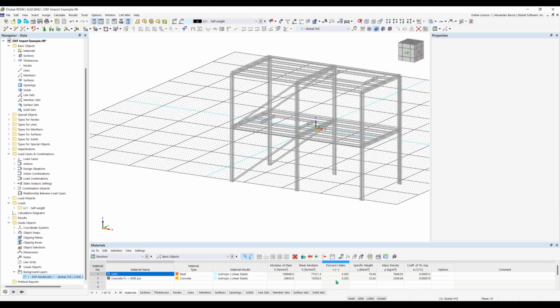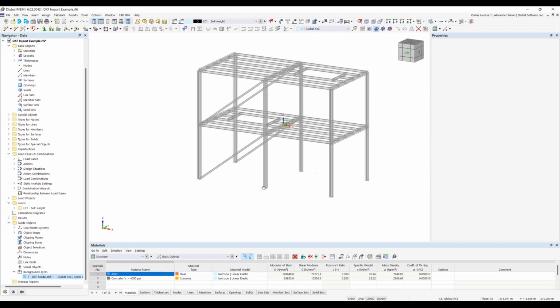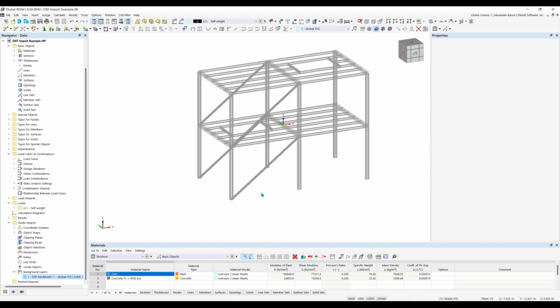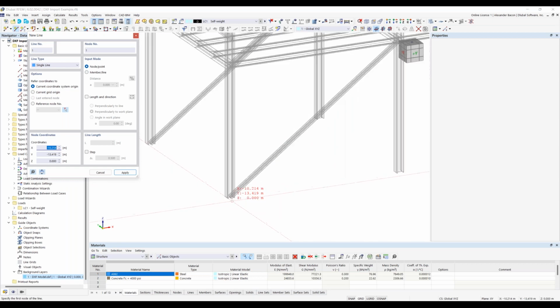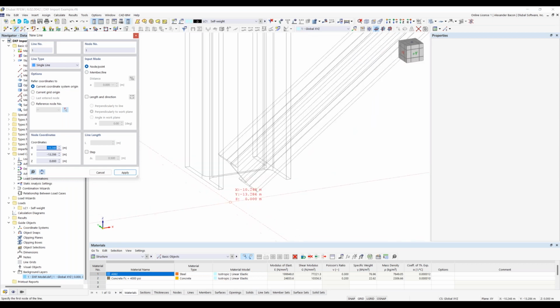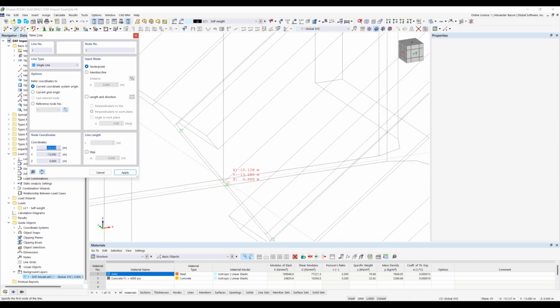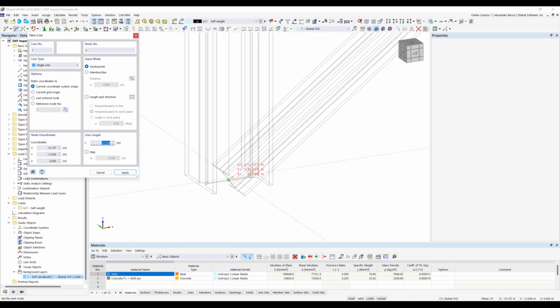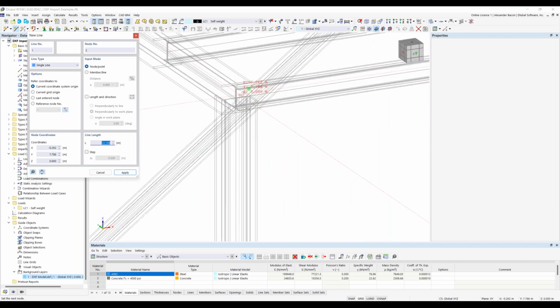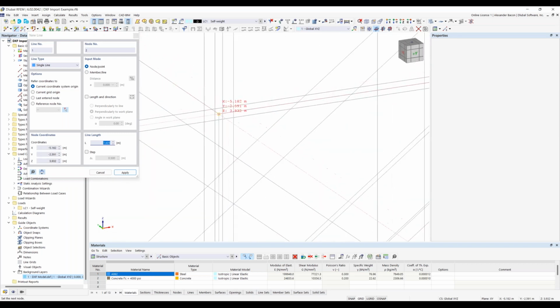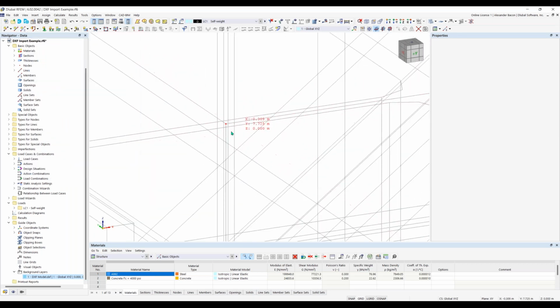So now we can use these background layers to model this. This is similar logic to the IFC file that I showed. And I'll just do an example real quick. So we can draw a line, a center line again. I'm going to use this column again as an example, so I can zoom in here and snap to this point if you have your object snap settings turned on. And then I'm going to go to the top here and I can snap to this point,